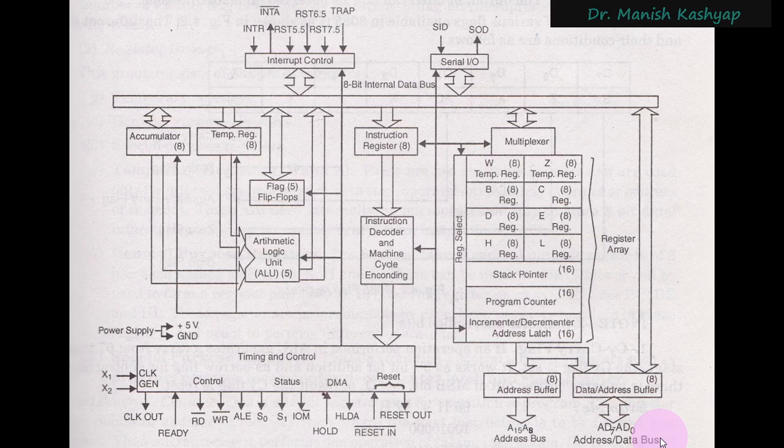Yes, there is a maximum limit for every computer depending upon its architecture. So here also you can see that 8085 allows you to connect a maximum of 256 input output devices whose port addresses will be again from 00 to FFH, right? Because if you are trying to connect 256 devices, you can just represent them by using the numbers from 0 to 255. So the port addresses will be in that range only, right?